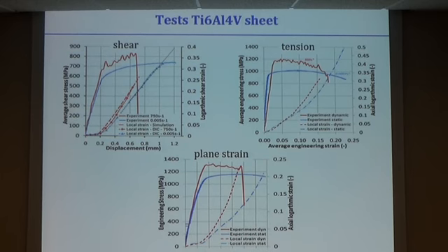You reach a certain maximum stress level or maximum force level, and then you have localization of the strains in a very limited region around the center of the sample. One exception: the dynamic shear experiment. There we had adiabatic shear banding, so during the hardening stage we had immediate failure, no stage of unstable deformation as in the other cases.